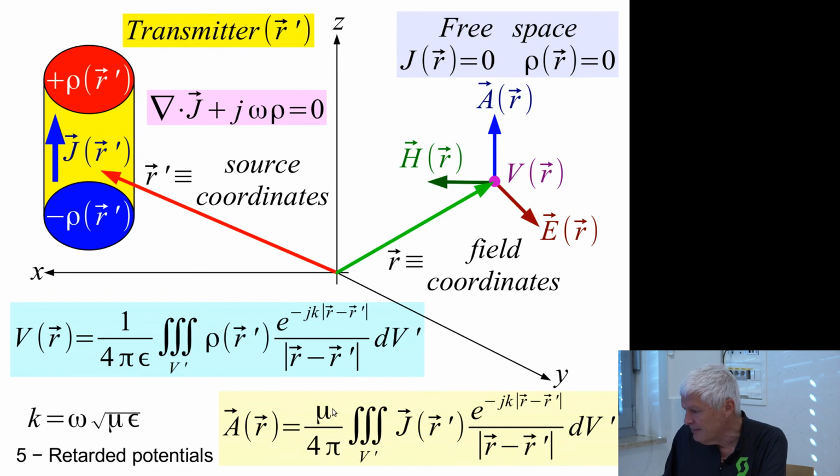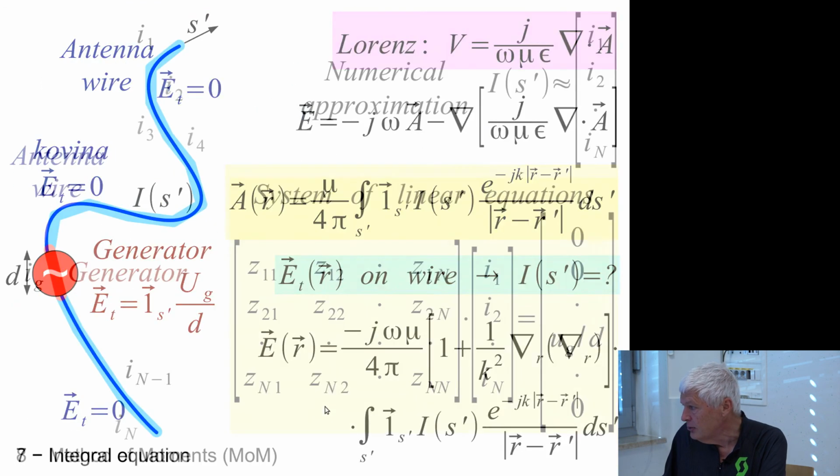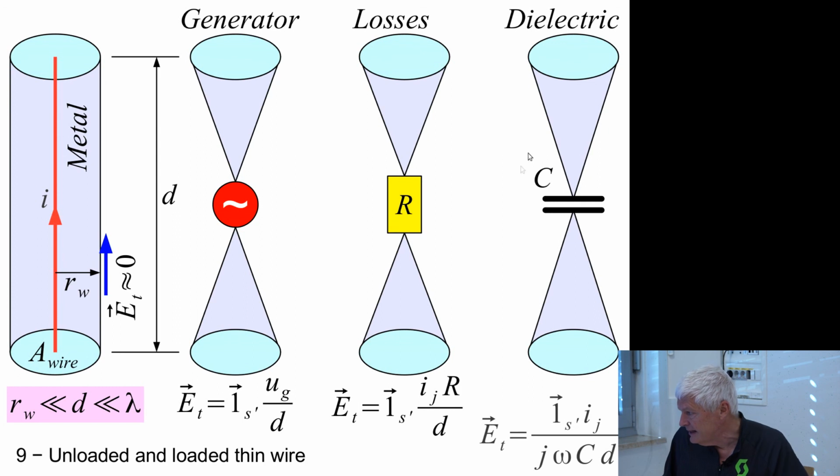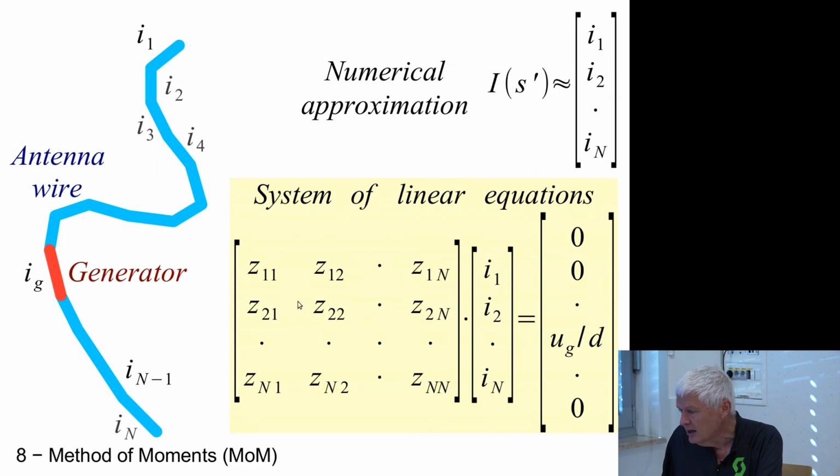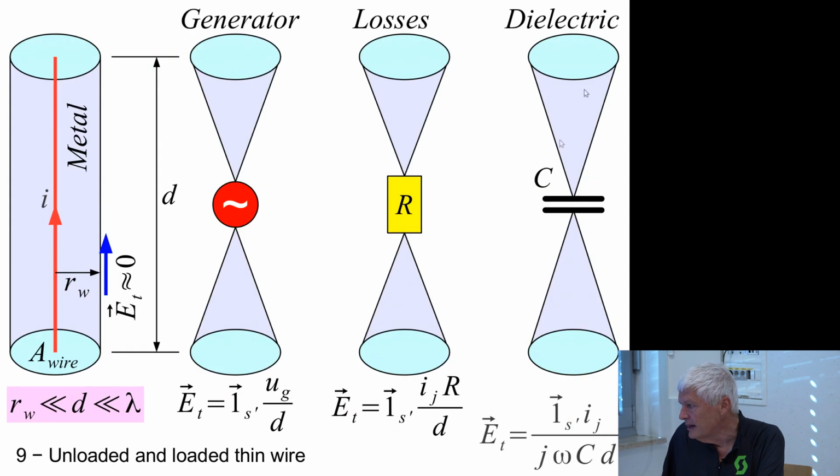If we have some additional dielectric, then we can model that dielectric with additional capacitors inserted in our structure, and that's the trick. So we can extend our method of moments also to space that contains some dielectric. And that's the important point for us. And I'm going to show you later on in the next 2 hours what we are going to do here.